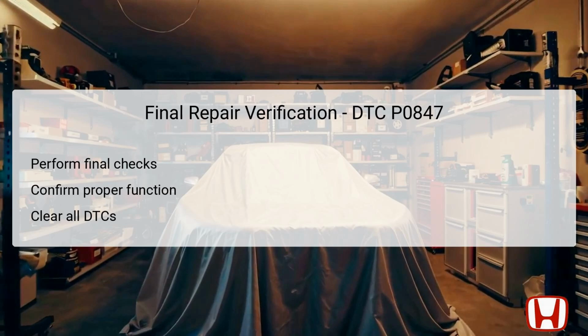Using HDS to clear any stored codes once more will confirm that your repairs have resolved the issue. After confirming a lack of active codes or errors, perform a test drive to evaluate the transmission's behavior in various driving conditions. Properly functioning transmission fluid pressure switches should provide stable signals and allow for optimal gear shifts without engagement problems.